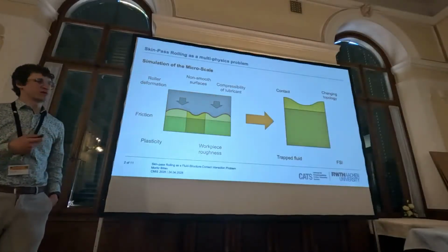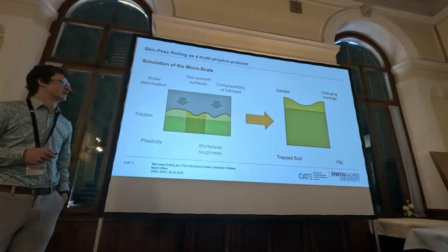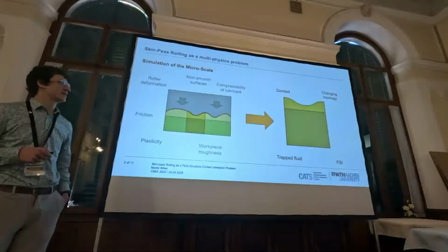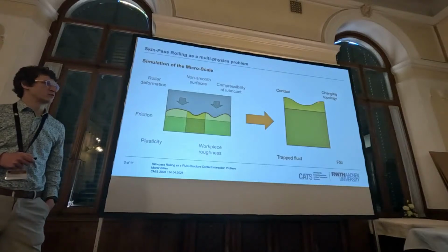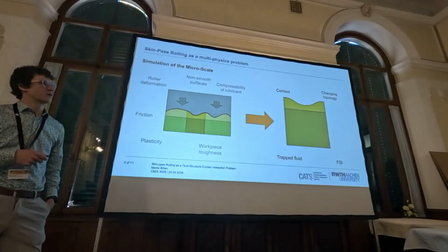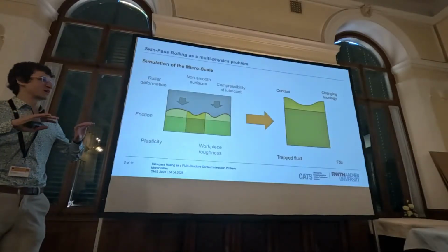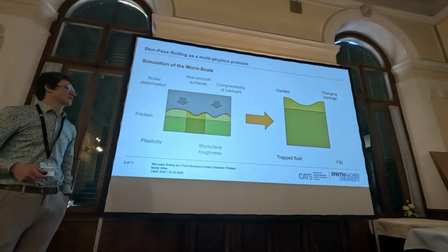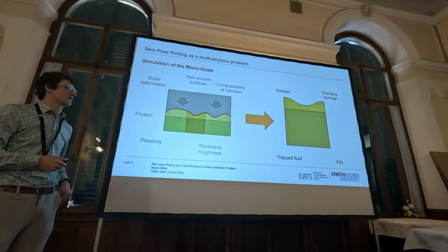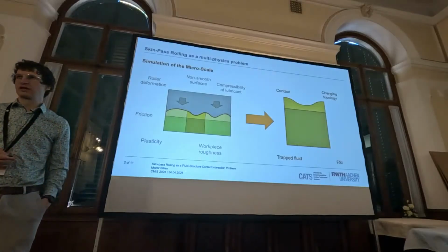But we simplified the problem, and I already show here the geometry that I'm analyzing later. We are considering contact, a changing topology. If this roller surface is moving down and we have contact, the fluid domain splits in two and we have a changing topology. This also traps the fluid if we consider this closed on one side. And there's obviously FSI involved.